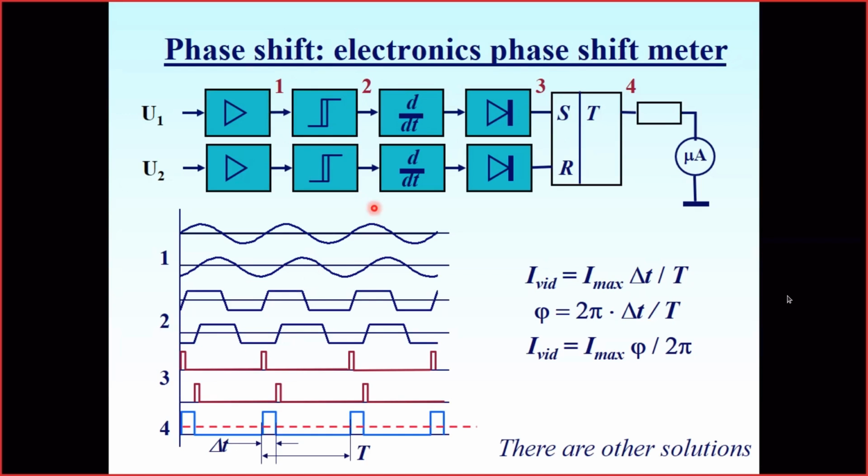So we got this, and after the differentiation and rectification, we get pulses. It depends on how we orient our scope, or when we drive our scope with a positive slope. So we connect this diode in a forward direction and cut out all the negative pulses.